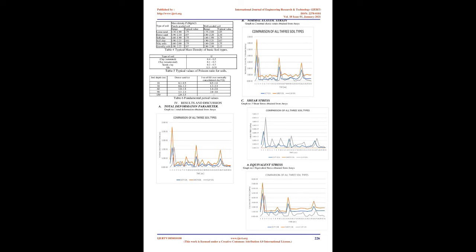Dynamic equilibrium equation. When the structural configuration is complex or significant dynamic interaction between interconnected members cannot be avoided, a coupled analysis approach can be used. The coupled analysis approach can include as few as 2 degrees of freedom to represent a structural system, or it can involve the use of many degrees of freedom in a single, comprehensive dynamic analysis of the entire superstructure. Responses of MDOF systems are determined from the solution of the following dynamic equilibrium equation.